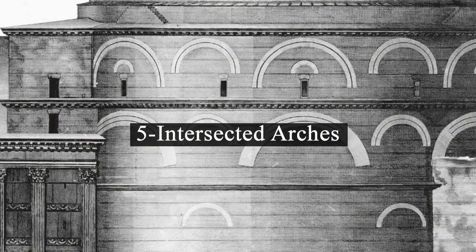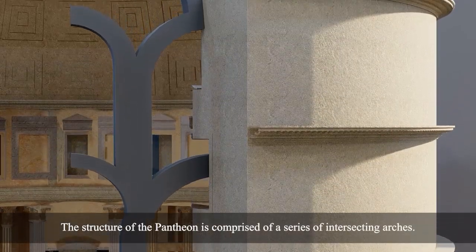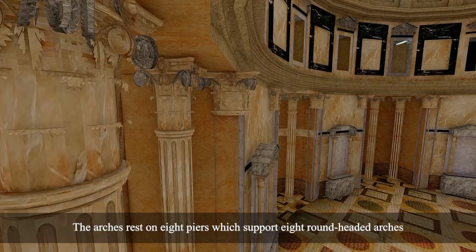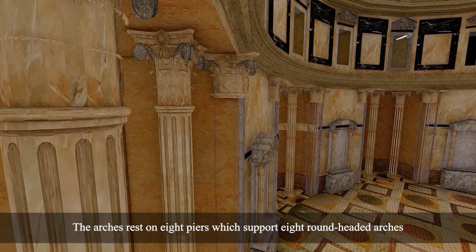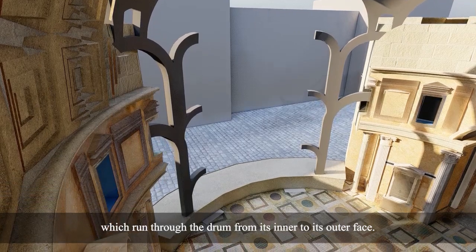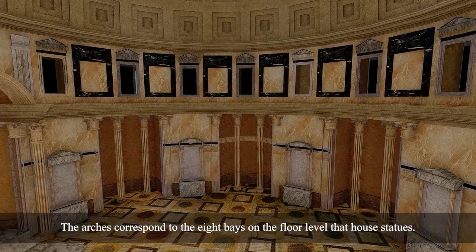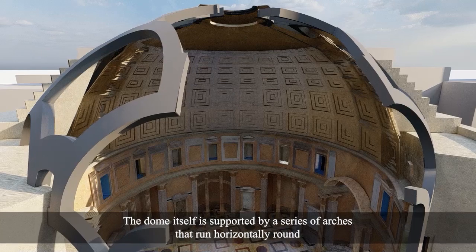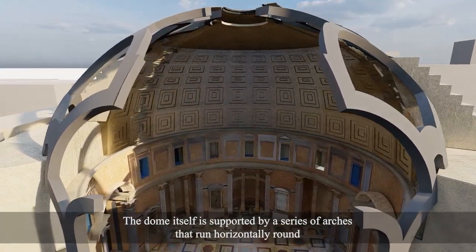The fifth element is the intersected arches. The structure of the Pantheon is composed of a series of intersecting arches. The arches rest on 8 piers, which support 8 rounded headed arches which run through the dome from its inner to its outer face. The arches correspond to the 8 bays of the floor level that house statues. The dome itself is supported by a series of arches that run horizontally round.